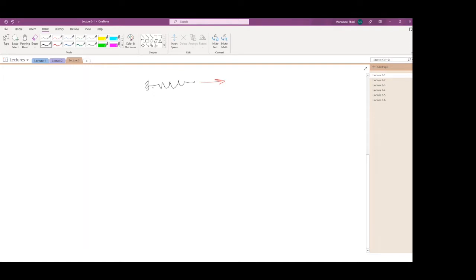Now, Hooke brought a spring, fixed one end, and applied a force at this free end, and then he measured the displacement resulting from the force. Now, he did the experiment for multiple forces and multiple displacements. He found that for a force F1, this is F and this is displacement, you get this point. So you get a displacement of U1. For a force F2, you have a displacement U2, and so on. And he observed that as long as you don't break the spring, all these points will happen on a line.